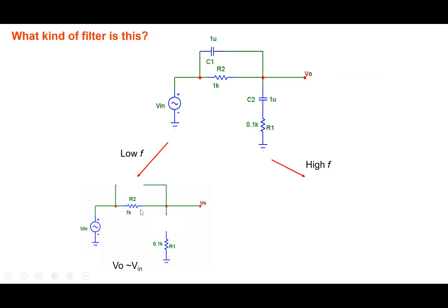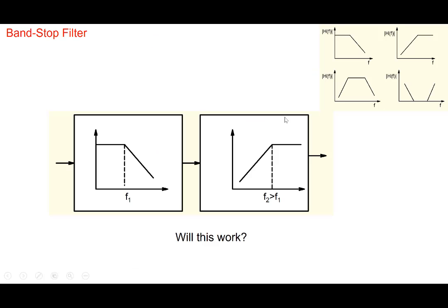That's why, when we have drawn here, if we go back, this would be an ideal filter if it were constant, and at this particular point it abruptly drops to 0 or a very, very high value here, right? So this is not so gradual, but attenuates or rejects all the unwanted frequencies and perfectly passes all the wanted frequencies, right? So that would be an ideal low pass filter, a rectangular shape like this. An ideal high pass filter would be constant here and then abruptly drop here, right? The more gradual the attenuation, the less useful the filter is in attenuating the unwanted frequencies, right?